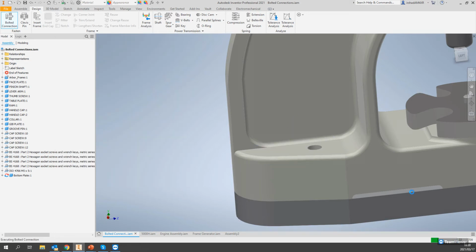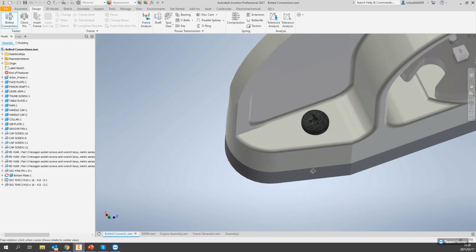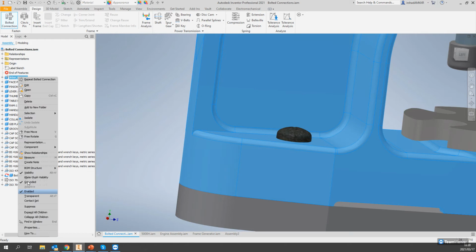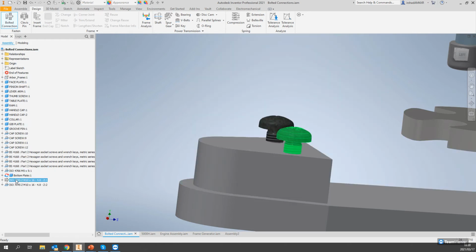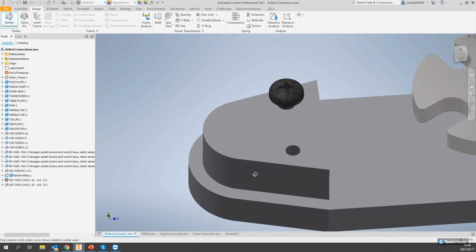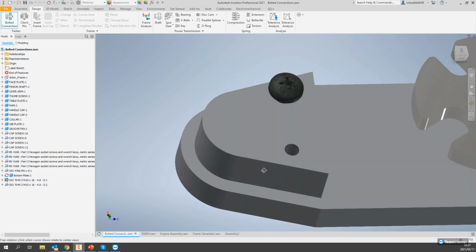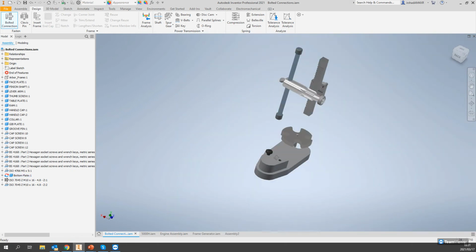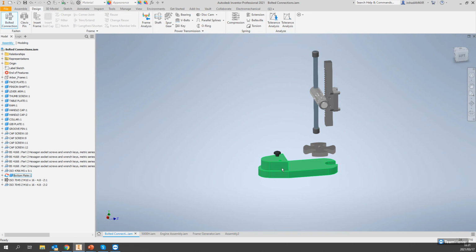And you'll see it'll calculate all of these things, making sure that it's placing it in the right place and also cutting out the holes for me. So you can see I've placed my screw in there. And if I hide the visibility of that, and perhaps that as well, we can see that it's made the hole for us based on our requirements with the correct threading applied. So you don't always need to design your parts fully if you know that you're going to be putting some sort of fixtures or fasteners in there, because the design accelerators can help you with that.